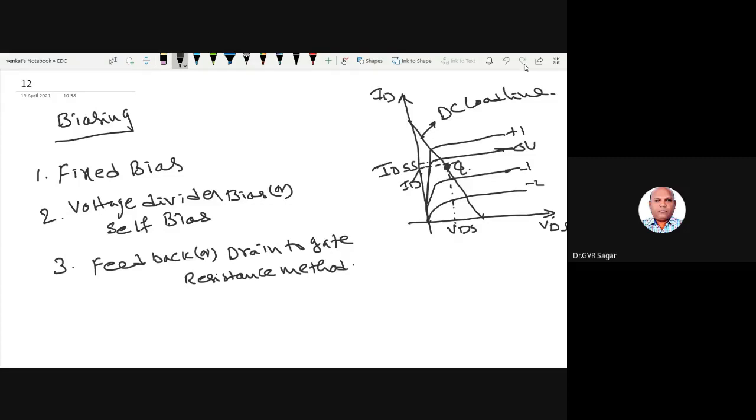So here, the same thing, we have to keep this operating point, because the operating point may also change in the FET. Why? In the FET, the two gate junctions are reverse biased. We have taken it like this. In the FET, there is a reverse bias junction, the P here is in the channel, right? So this depletion is forming here, and a narrow gap is here. This is called the pinch off region.